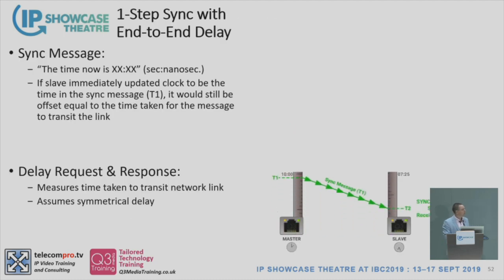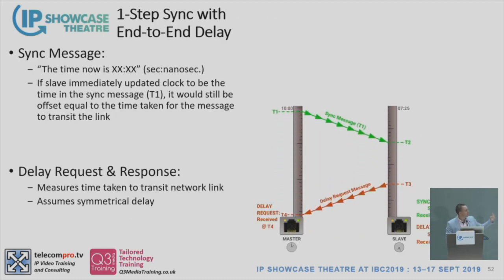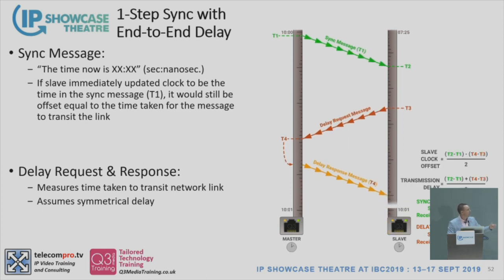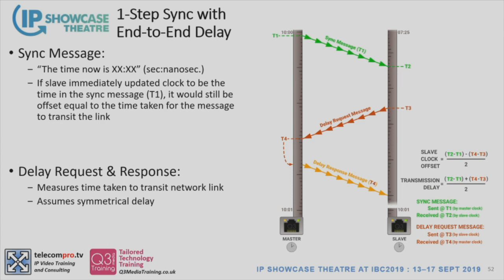So if we look at what's going on between a master and a slave on a PTP network in terms of the messages going back and forth, in its simplest form, the messages would look like this. Coming from the master, a sync message: the time is 12 o'clock. The slave receives that, and it knows it received it at what it thought was, well, I thought it was 11:58, but okay. At 11:58, you told me the time was 12 o'clock. Great, okay. Now let me figure out how long it takes the messages to get between master and slave.